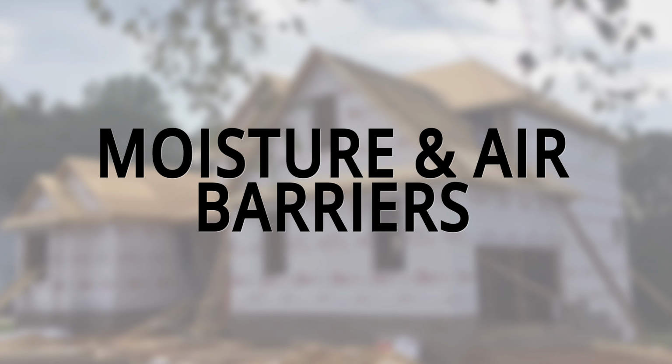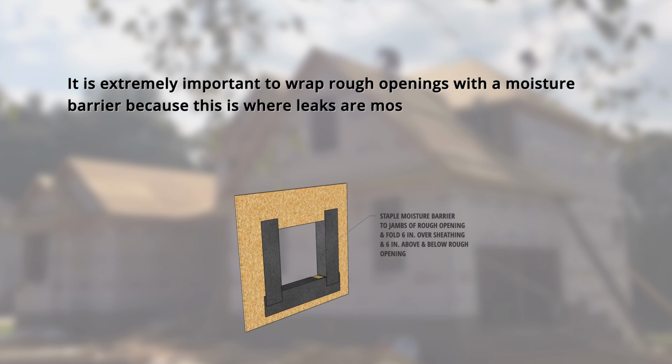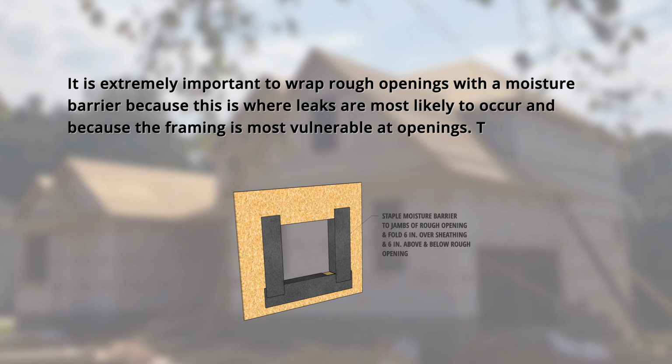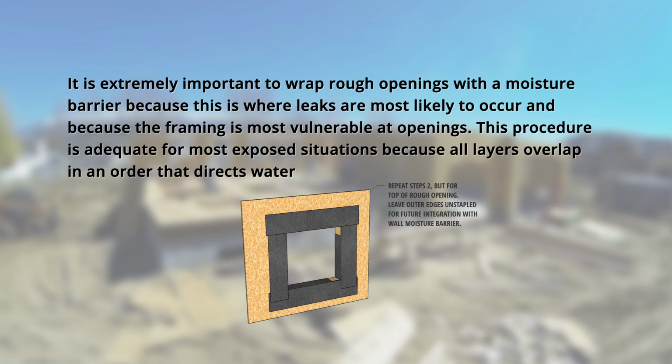Moisture and air barriers. It is extremely important to wrap rough openings with a moisture barrier because this is where leaks are most likely to occur and because the framing is most vulnerable at openings. This procedure is adequate for most exposed situations because all layers overlap in an order that directs water away from the structural frame of the building.